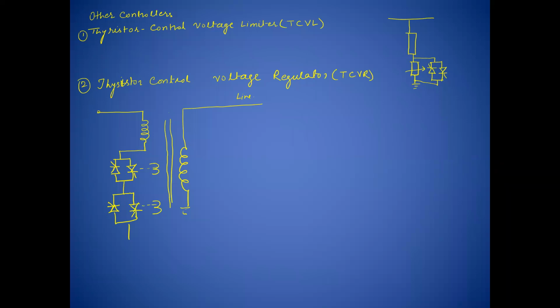In the previous lecture, we discussed a brief introduction of different types of FACTS controllers. Either the controller may be connected in shunt, that is called a shunt controller, that is STATCOM or static var compensator, either thyristor controlled or thyristor switched static var compensator. Similarly, in the category of series, it is a static synchronous series compensator, or it may be a thyristor controlled series compensator, or it may be a thyristor switched controller, which we have already discussed.